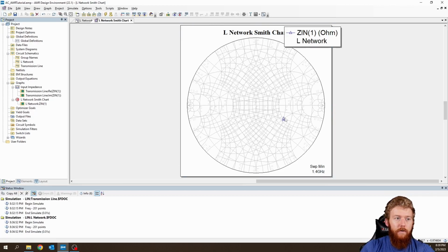This first one will require us to add an inductor, since we're moving up in the Smith chart, and back down with a capacitor. So it could be an inductor and then a capacitor. And if we check this one, it'll be adding a capacitor and then an inductor, since we're going down and then up. Now, something that's important to note is that since we're moving along this line in the admittance grid, that's going to be the constant conductance circle.